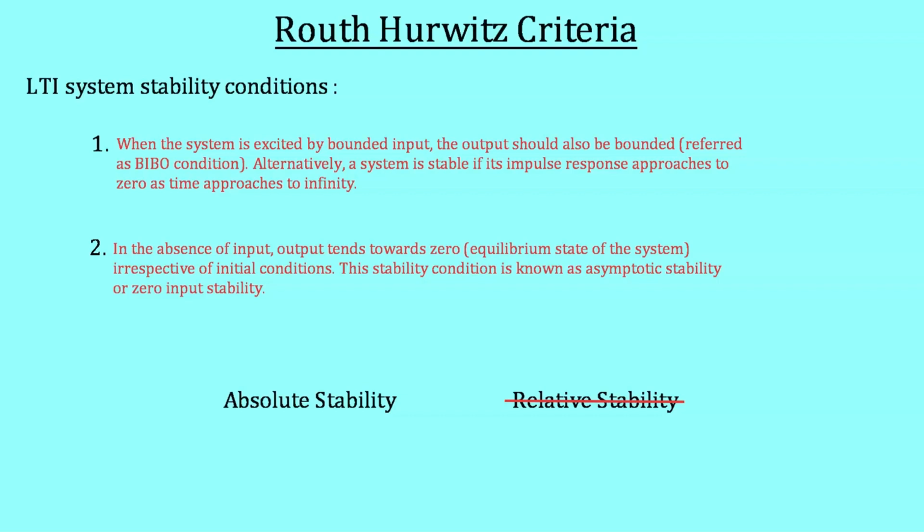If you think carefully, then you will realize the stability is also dependent upon the input, but that point is also covered in the first definition of stability of an LTI system. As you can see, we have to follow the bounded input, bounded output condition. But again, it is practically not possible to consider all such bounded input signals.